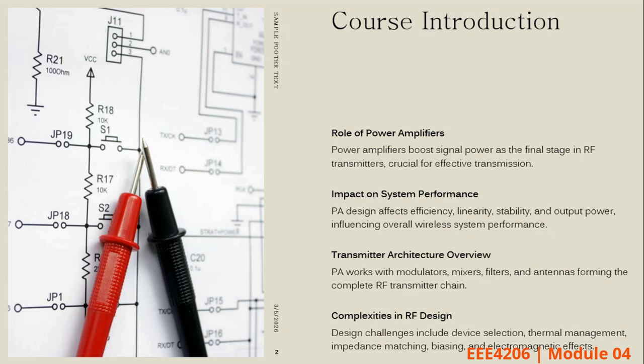So before we transmit it into the antenna, it needs to be boosted to a level that you can recover the signal. The power amplifier in RF systems is the final active stage in the transmitter chain, and its purpose is to deliver sufficient signal power to the antenna while maintaining acceptable signal fidelity and also efficiency.